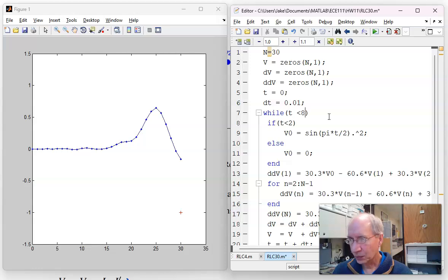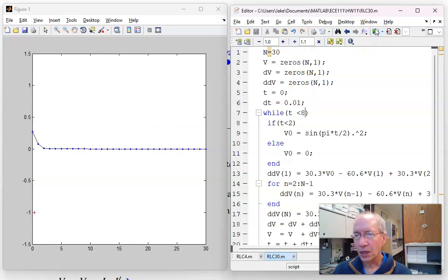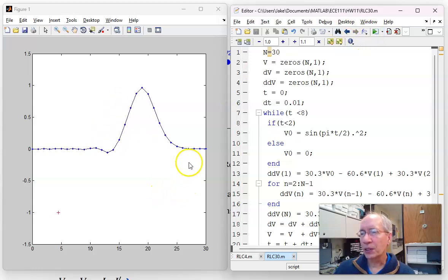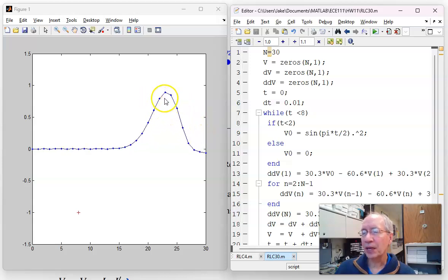I'm going to launch a wave, the wave travels down the waveguide, travels down the RLC circuit. That's my voltage propagating down. When I hit the right endpoint, watch what happens. This is a free endpoint. It snaps up to double the amplitude, comes back down to 0. Then I get a reflection. The reflection is the same amplitude and same sign as it came in.